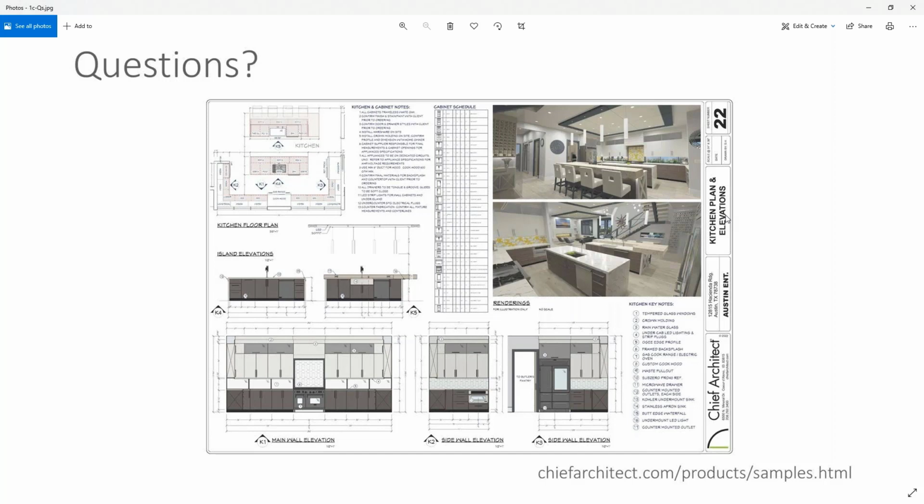Well, a couple things. First, let me just respond to the last caller. One thing that I do often, because I use a lot of different finishes sometimes for cabinets and they can be in different rooms, is I just make my own custom schedules. And then when you go into the cabinet, you can just assign what schedule that cabinet is going to go to.